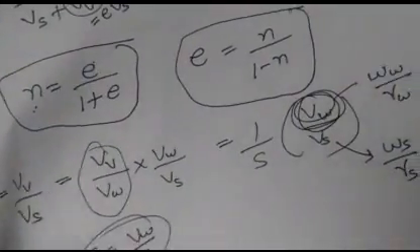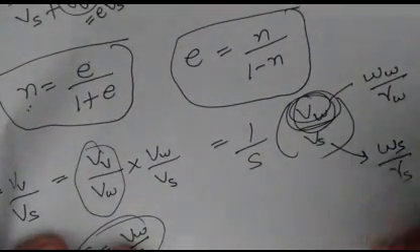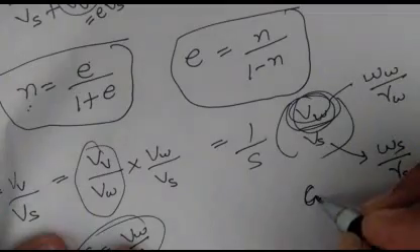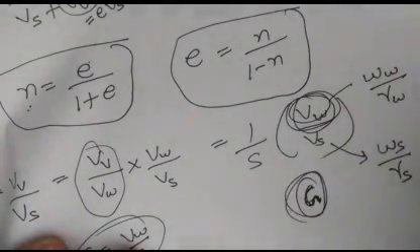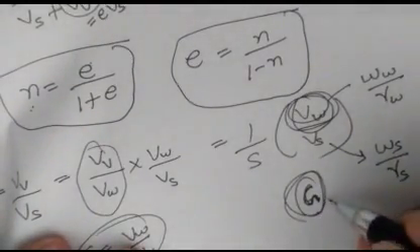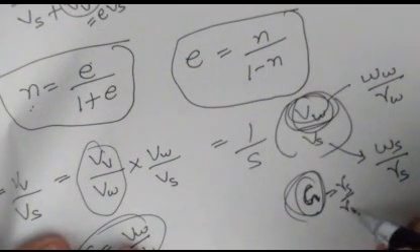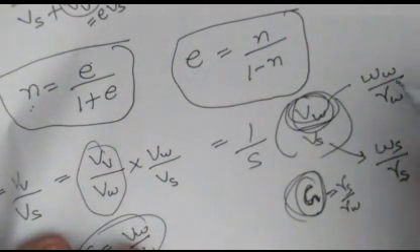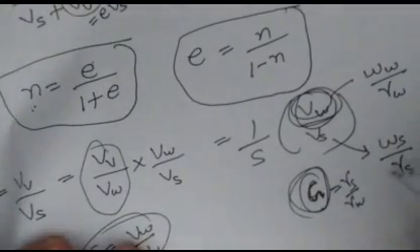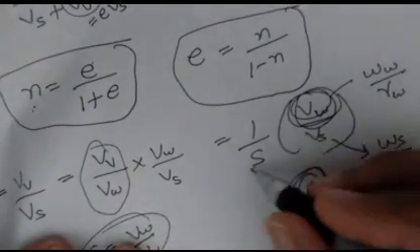Actually, I am looking forward to introduce a specific gravity in this formula, G. So if I want to introduce G, what is G? G is equal to gamma S by gamma W. So I will get G from here. And what is this? WW by WS. It is water content, W. So actually I am introducing two terms here, G and water content, and S is there.